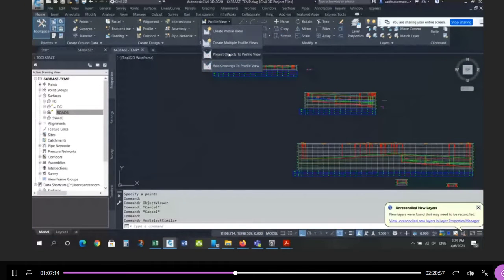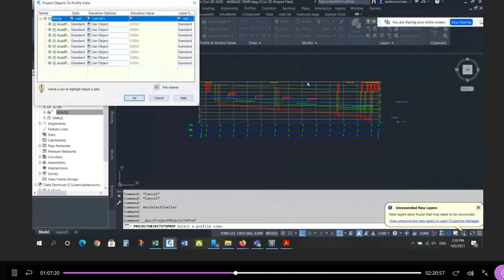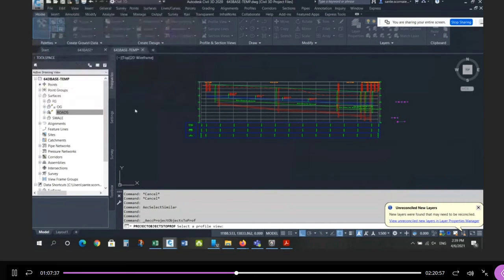You've done this before, right? Projecting points from plan to profile. We use this technique for modeling our corridor elbows. I'm going to put it here. The elevations are all garbage, so I'm going to use my original ground. I just need the station values. I'll worry about the elevations myself. So it's the stations that are okay, but the elevations. If you use 0, then your grid's going to expand, right? Because it starts at 190. So make sure you bring them in range, same as before.